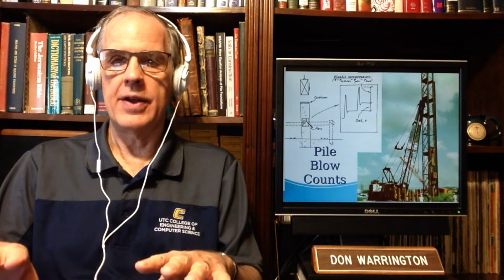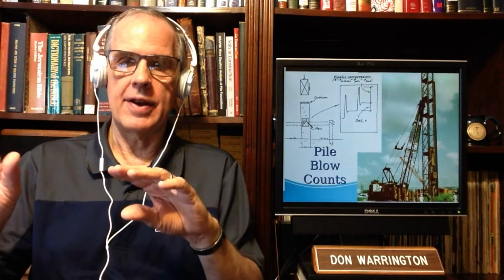It's not just the elastic compression of the pile, the soil also has its own elastic and elastoplastic compression. What that does is store energy. You have energy, leaving out losses in the driving system itself.